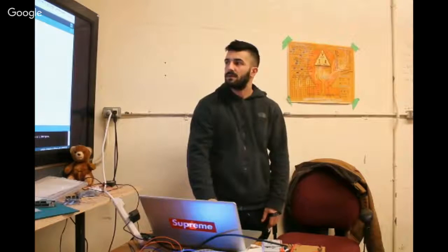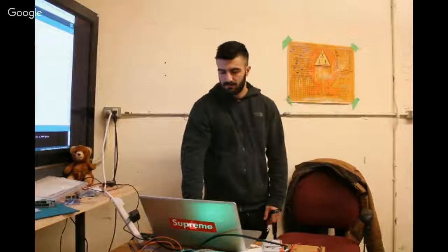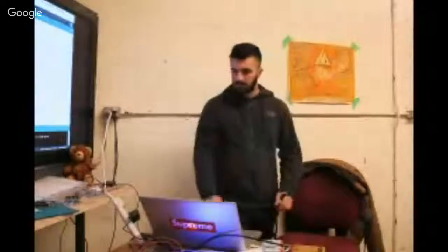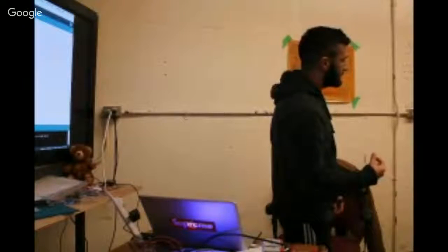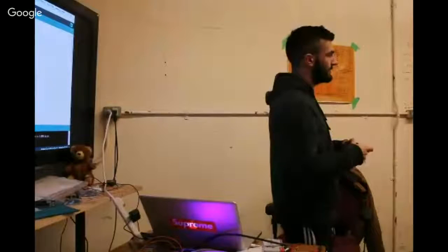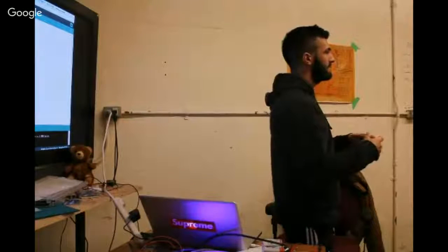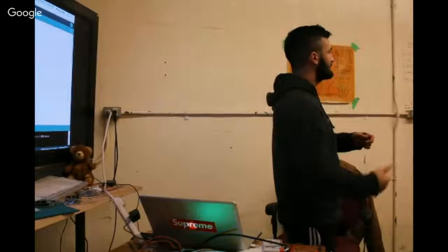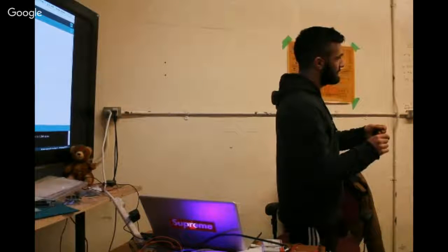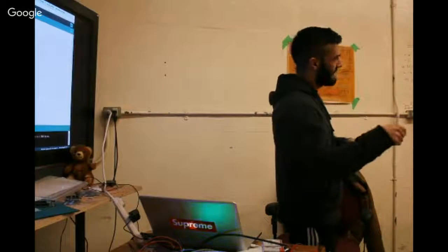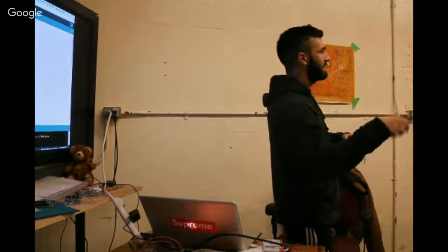Can I just ask, because you're going from a battery to the 120-volt power plug. What's powering the Arduino? So what's happening here is there's a voltage regulator. So basically, we have the Arduino, a relay, and a voltage regulator. It'll take power from the plug and convert it from AC to DC to power the board. And then from there, we do everything else.